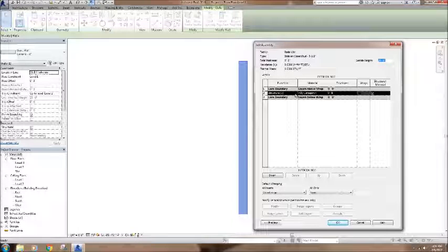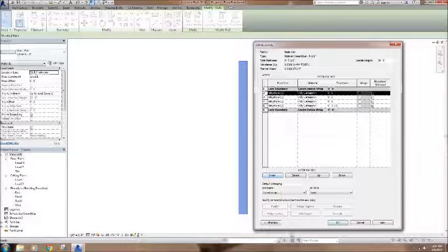What I'm going to do is change this to 3.5 inches. Since this is my structural layer, this will be my wood stud layer. And then I'm going to insert a couple layers here. So I'm going to make this 7/16 inch OSB, and then I'll end up with, say, a 1-inch air barrier or air gap, and then I will have 3 5/8 brick.